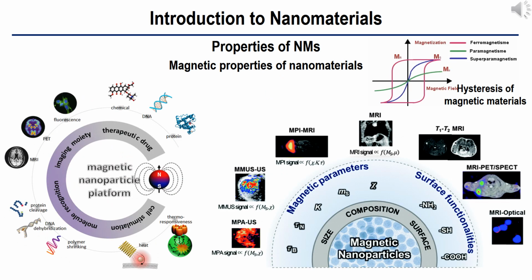The size of magnetic nanoparticles also influences the value of magnetization. For example, the saturation magnetization of zinc ferrite increases with decreasing the size of the nanoparticles. The magnetization increases significantly below a grain size of 20 nanometers. Hence, by decreasing the particle size of a granular magnetic material, it is possible to improve the quality of magnets fabricated from it. Bulk gold and Pt are non-magnetic, but at the nano size they are magnetic.